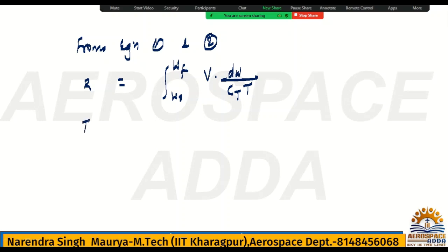What is the thrust? That is nothing but drag. And I told you how to manipulate this drag value. What can you write for the drag? Simple. You can write W into D by L, which is nothing but W into CD by CL. Also you can write, it's your choice. What R will you get?